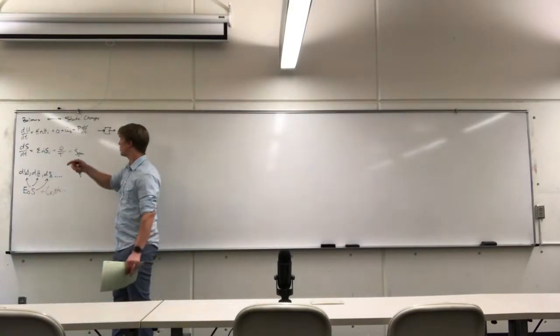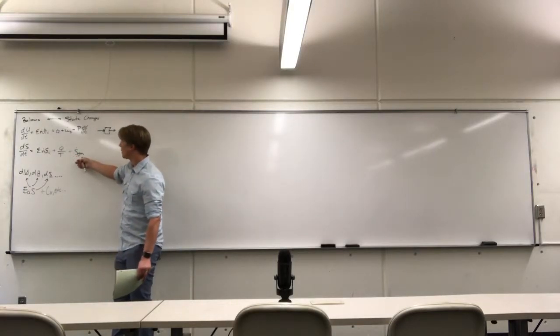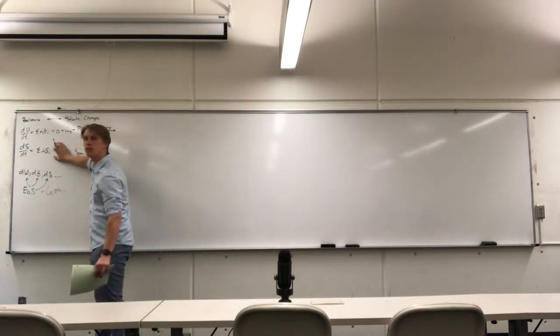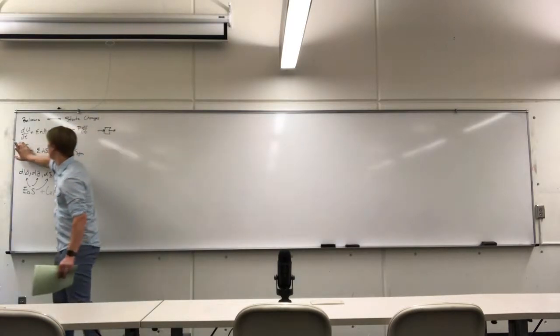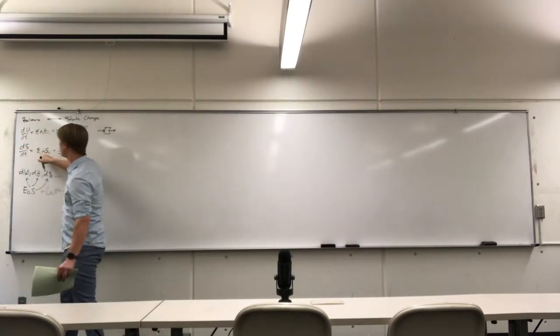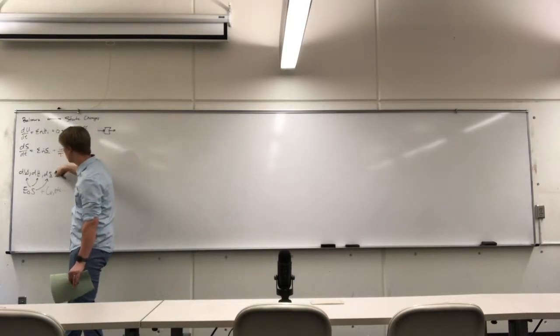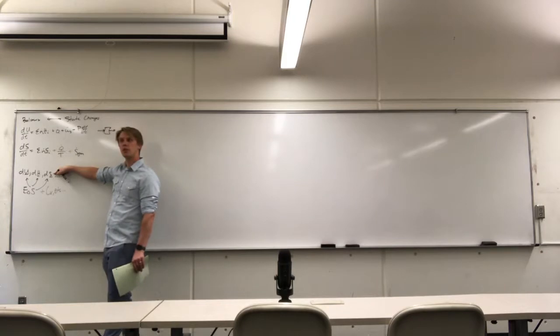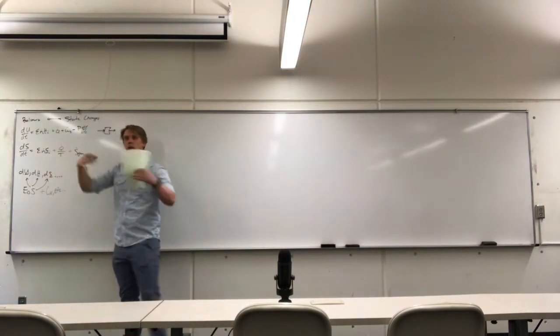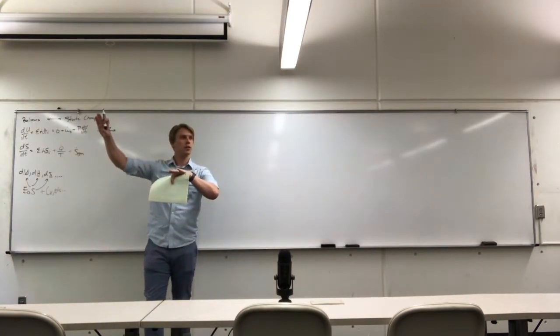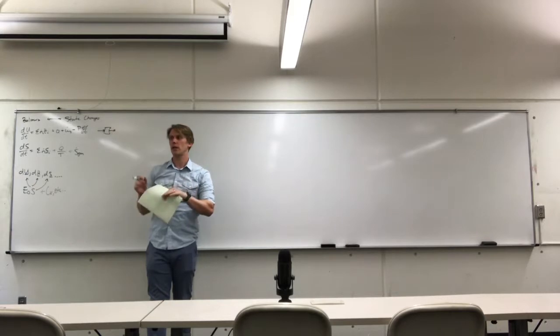We're going to be dealing with systems where we're going to say it's a reversible process that's adiabatic. So if it's reversible, this goes to 0. If it's adiabatic, this goes to 0. If it's steady state, this goes to 0, which tells us that the entropy in has to equal the entropy out. We take that knowledge, we then say dS has to equal 0, and based on whatever we expanded it with, let's say temperature and pressure, then we can derive a relationship for how the pressure and temperature have to follow a very set definite curve that allows us to run the process isentropically.